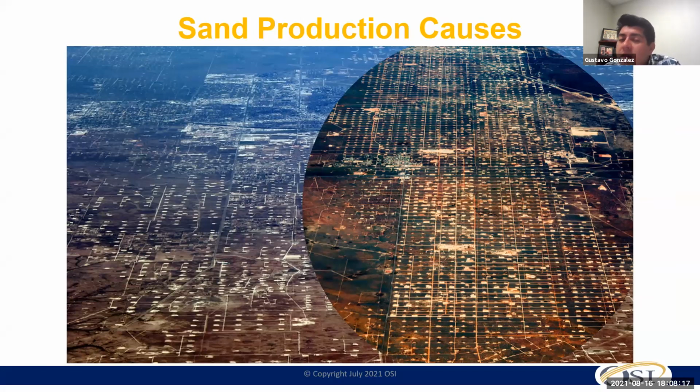That's always a good idea: design your artificial lift system to be able to handle that sand, because you cannot make disappear the sand that you either used to frack your well, or that is your formation sand coming through. Either you design your pump to handle a portion of the solids, or you find accessories or alternatives that can help you handle that, improve your runtime, and decrease the damage in the pumps.